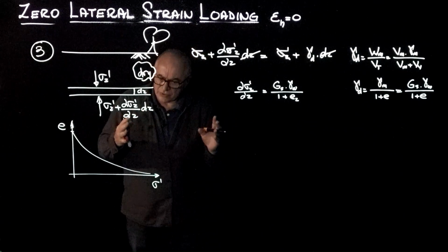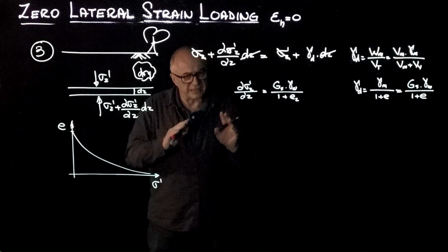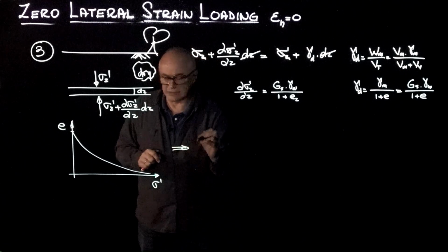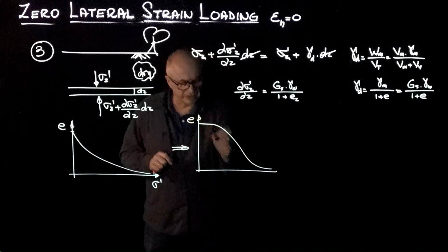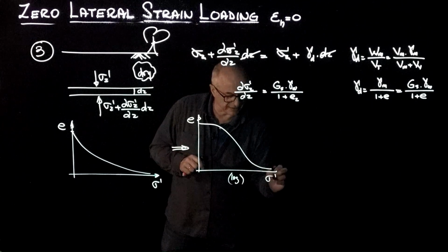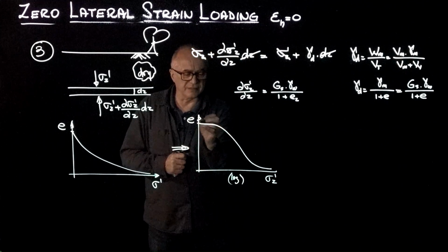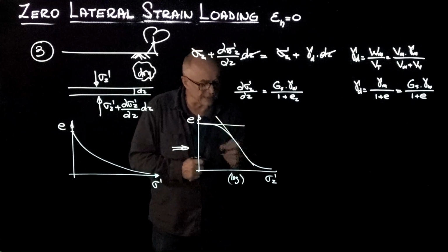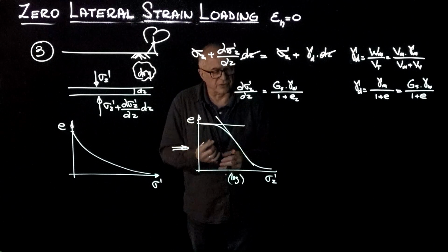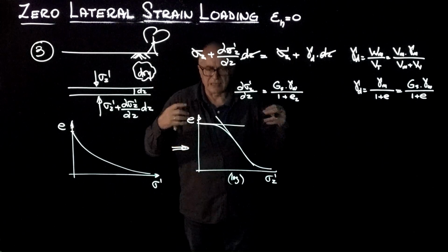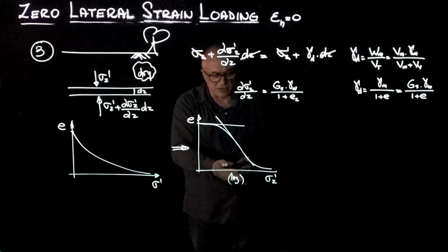However, we got used to the history of our field of plotting this in semi-log scale, which has some advantages, but be careful, there are some disadvantages as well. And when we plot in a semi-log scale, we see the trend behaves something like this. This is void ratio versus the logarithm of effective stress. Furthermore, what we have done in the field is we tend to fit this part with one slope and this other part with another equivalent linear system. And all this was very useful at the time, in the 30s and the 40s, when calculations were done by hand, without a computer, and everything was plotted in either linear scale, semi-log, or log-log.